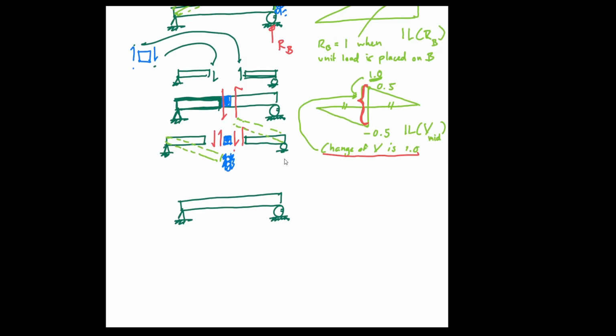Again, in the same fashion, I want to allow the moment in midspan to move freely without restraint. So what does that mean? It means that if you want the moment to move freely, that portion must be able to rotate, right? The moment is about rotation. So when you want it to move freely, you want it to rotate, and therefore you add a hinge. And again, we are talking about the sign convention of the positive moment. That is a positive one.